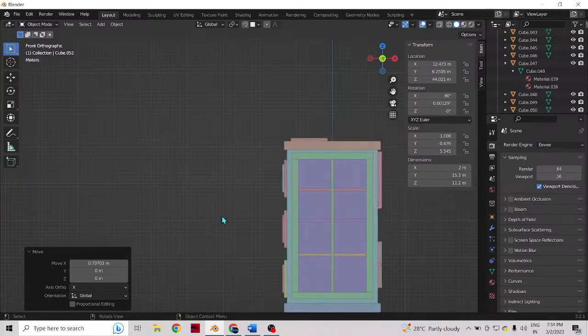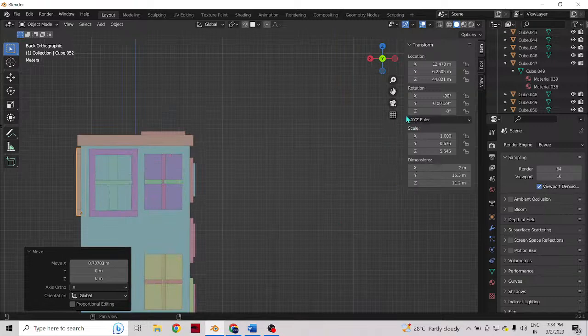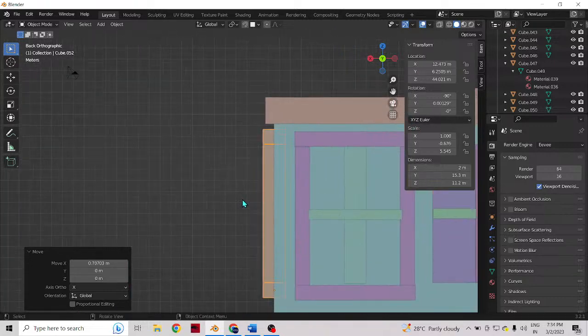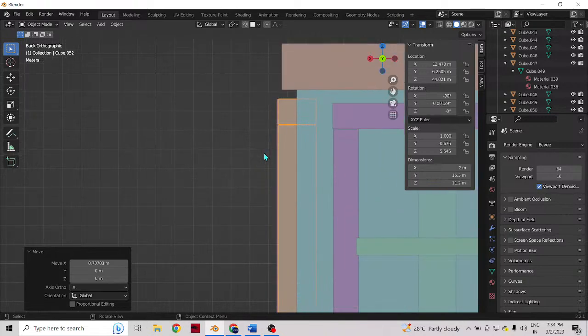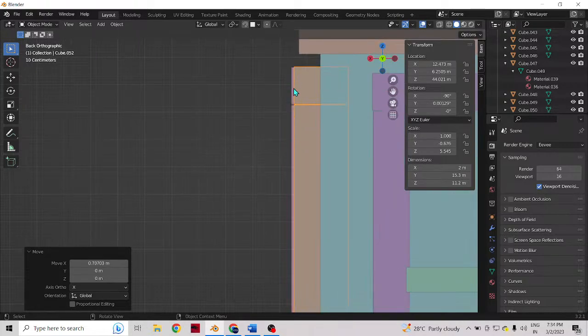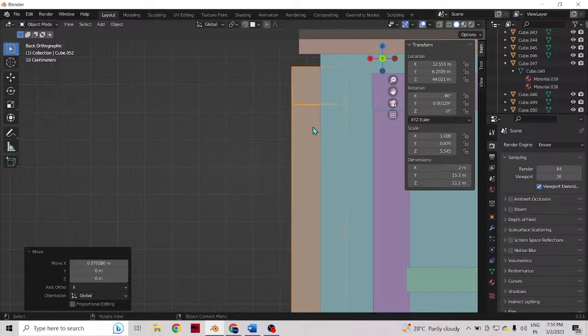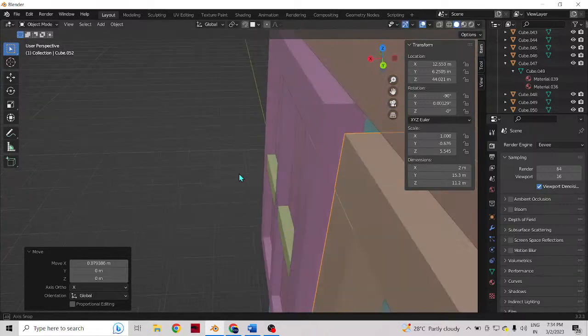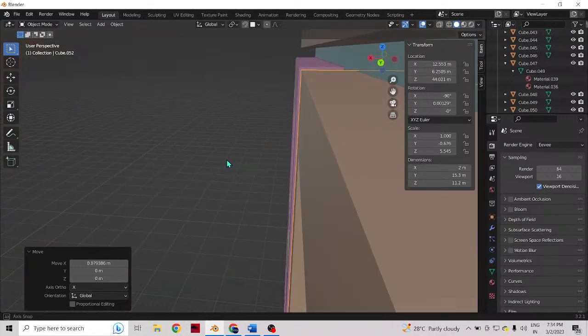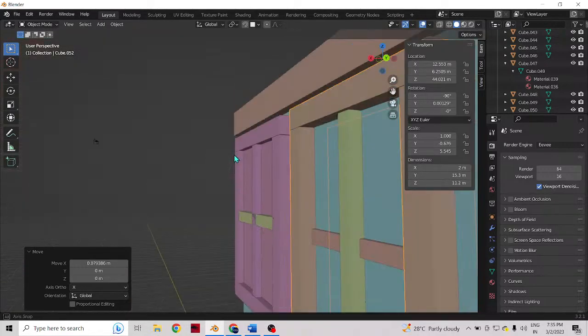To observe this, I'm going to the back view by pressing Control plus 1. Now I'm just observing the thing which is here. Here the pink color seems to be appearing. By knowing that, I grab it, and in the X axis I'm going to bring it a little bit forward so that the pink color vanishes, and now I know that both my frames are in equal place.